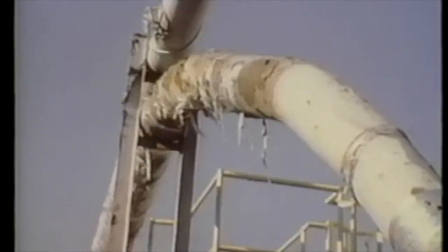Replace ductwork when it wears out due to erosion and impact damage from airborne particles. Maintain all ductwork in good working order. During design, remember to check with your local air pollution control agency to obtain a permit. The agency can give you guidance for selecting an air cleaner.